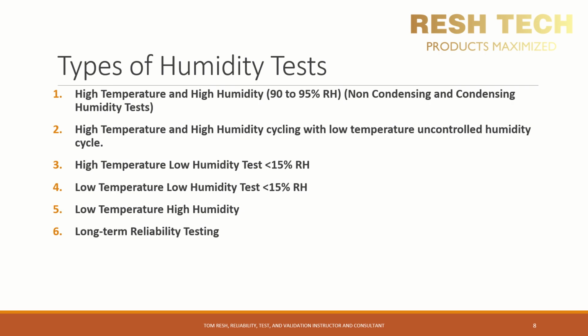Let's go ahead and cover some of the types of humidity tests that companies perform. The first type of test is high temperature and high humidity. You have non-condensing and condensing humidity tests. A non-condensing humidity test is pretty self-explanatory, as it indicates that the water vapors are not allowed to condense on your test samples.